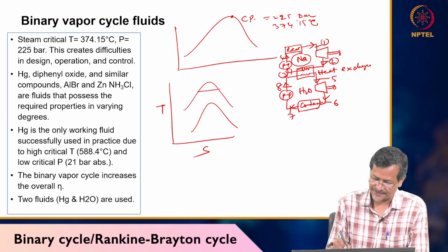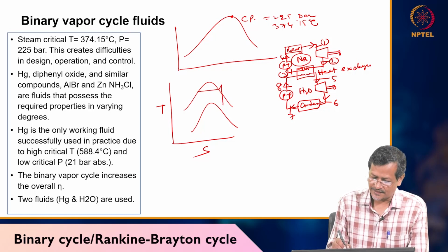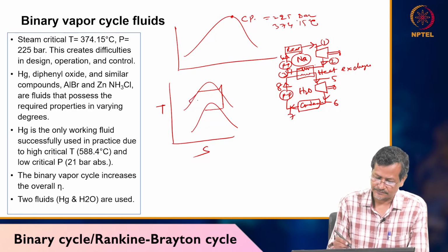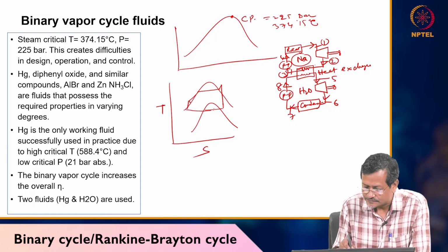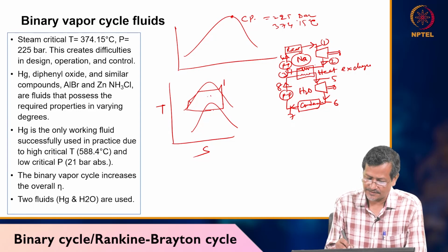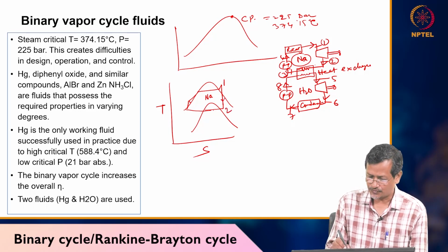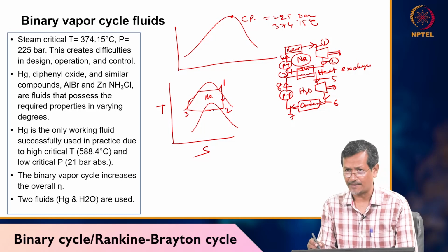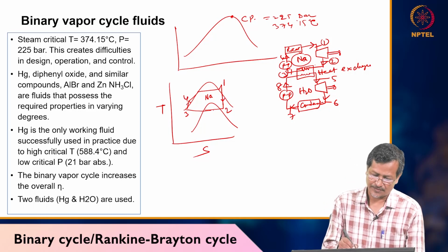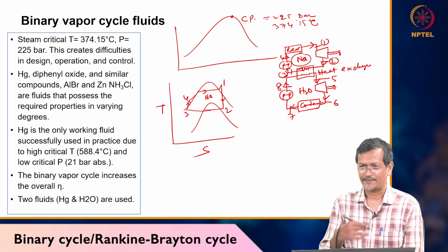So let's say my sodium cycle is here, maybe some superheat also there we are assuming. Okay, then turbine is taking power, then condenser will be condensing. Okay, then where is my pump? Okay, so where is my 1, it is here. This is the sodium cycle. Fine. 1 to 2 turbine, 2 to 3 my condensation happening. Okay, 3 to 4 pump working, 4 to 1 again your heating happening. This is happening inside the reactor.